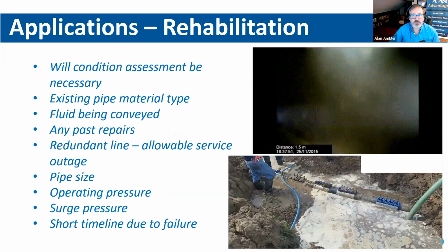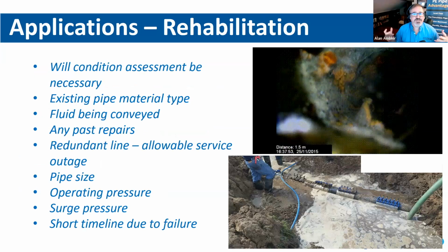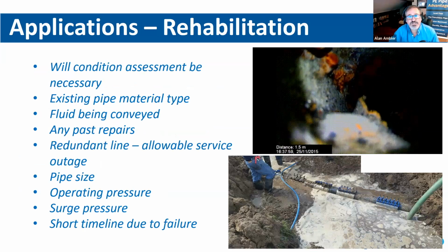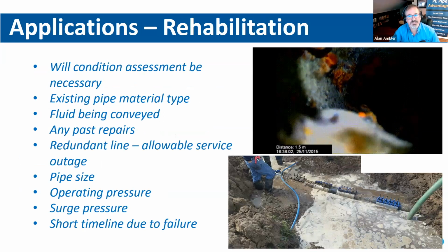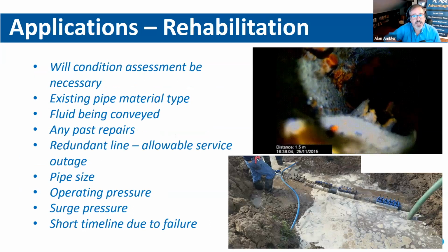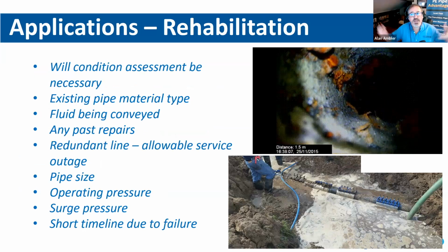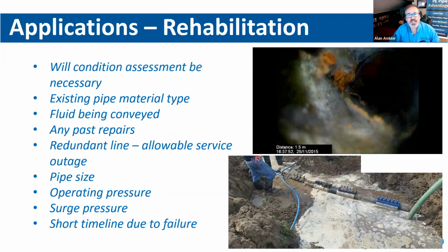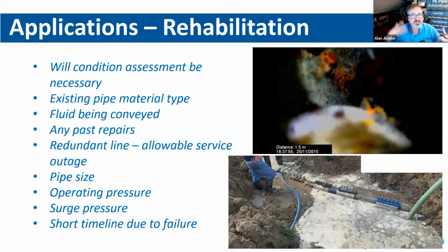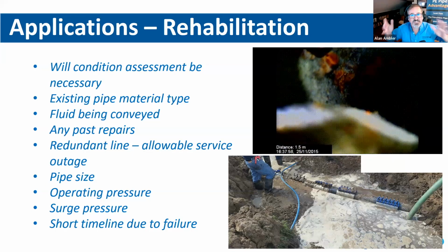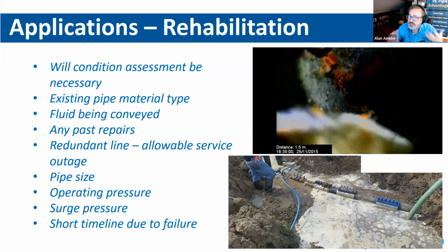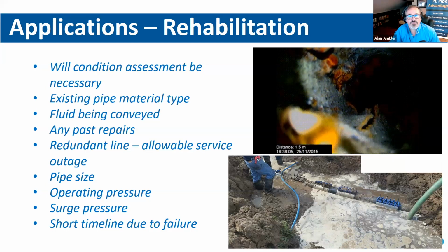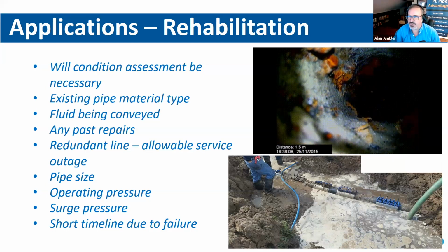So in rehab, what are we looking at? Is a condition assessment necessary? And pressure pipeline has different implications for condition assessment than gravity sewer pipelines. It's often very common to clean and CCTV inspect a gravity sewer at the same time, because that's what the manhole does, is provide us access to that line segment. In a pressurized pipeline, that pipeline is consistently under pressure, so we have to isolate it, dry it out, and perform those inspections, or there are some live inspections in order to make your way through that pressure pipeline under live condition as we go through.